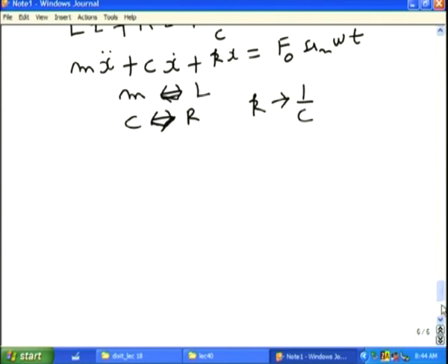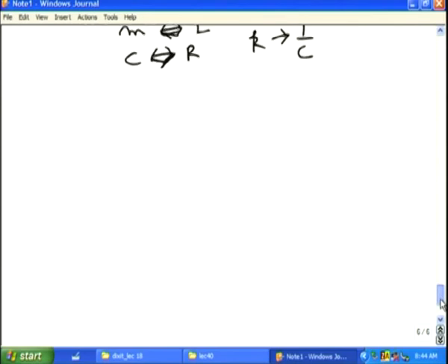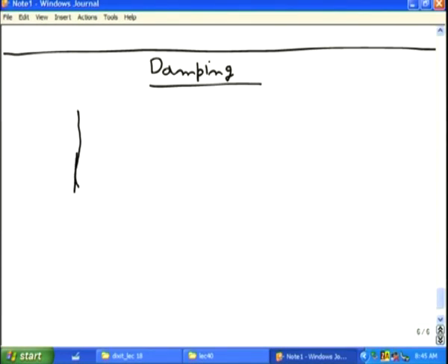Now, we have been talking about damping. It is difficult to determine damping. Spring stiffness can be easily determined. Take a spring, apply some force, see the deflection, force divided by deflection, use the stiffness. However, damping is not so easy to determine. One method employed for finding out the damping of a single degree of freedom system is like this.